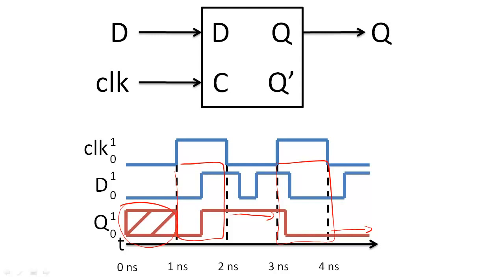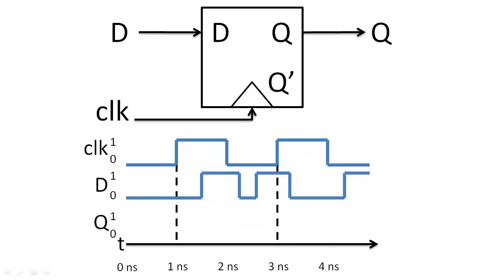This gated latch is not ideal though, because we must hold the data input at the desired input value for half of the clock cycle, and that cuts down the time that we have to perform calculations during the clock cycle in half. An alternative clocking method for synchronizing state storage components is called edge triggering. When we use an edge triggering clocking scheme, we call the latch a flip-flop.